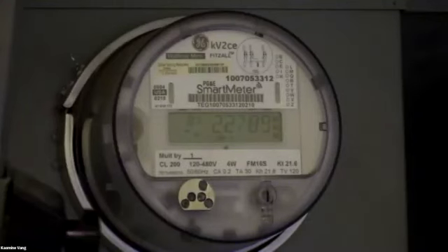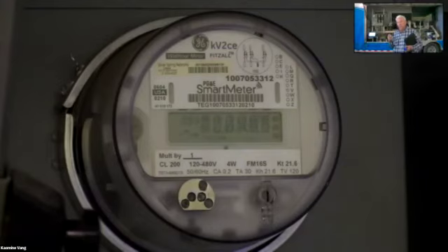Okay, that's our meter on our trailer right now. That's kilowatt hours. Here's kilowatts, 4.66 kilowatts. Now I could do the equation. You divide by 0.746 and that equals horsepower. It's about 6.1 horsepower, I believe. So our 5 horsepower pump is pulling more than 6 horsepower because of the inefficiency of the motor.